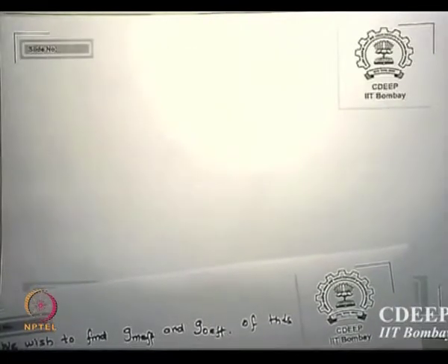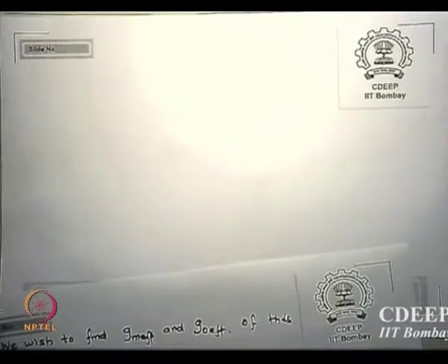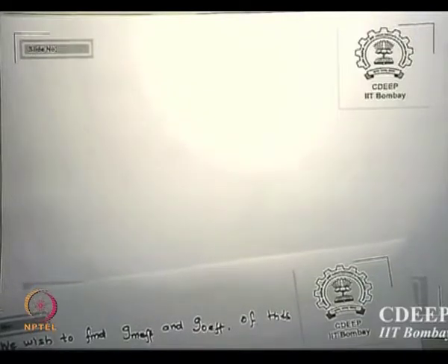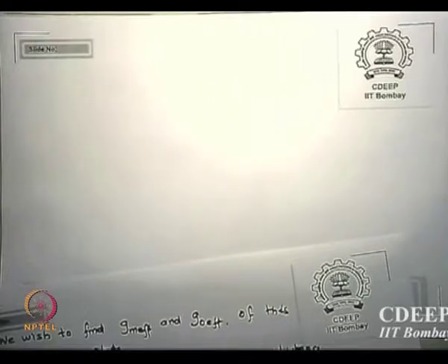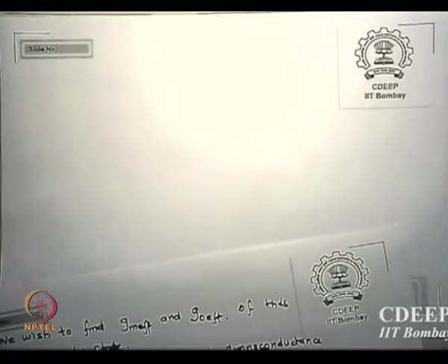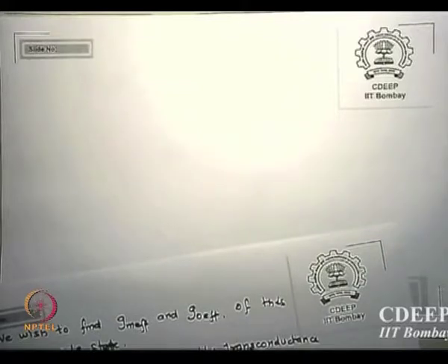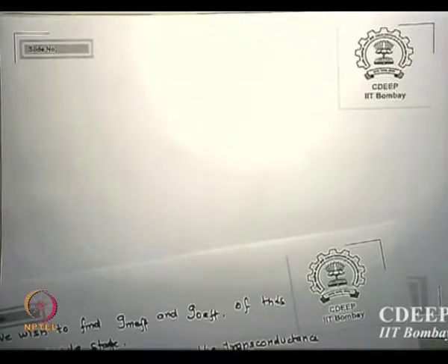Now I want to analyze what is the criteria I said last time to make cascode better than cascade. Normally I say FT or unity gain frequency, or the gain bandwidth product as we call it, GBW, is constant for a normal common source or any amplifier. So if I increase gain, bandwidth goes down, if I increase bandwidth, gain goes down, is that clear? And the maximum frequency is the unity gain frequency, is that correct? You can't go beyond that, because beyond that gain is in negative dBs, meaning less than 1.